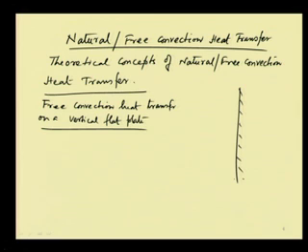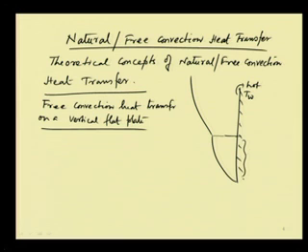What happens is that the plate is hot and it is maintained at a temperature of Tw. This is the kind of behavior as we have seen if you just give a 90-degree rotation, it is like flow over a horizontal plate. And in this region, we can say that this is the laminar region, and this is the turbulent region.